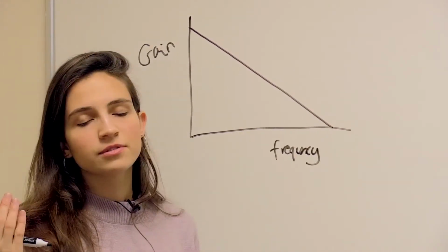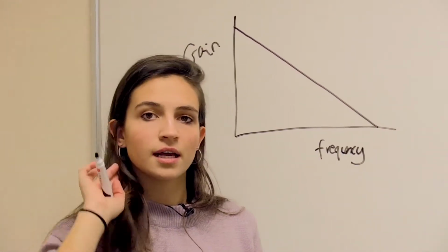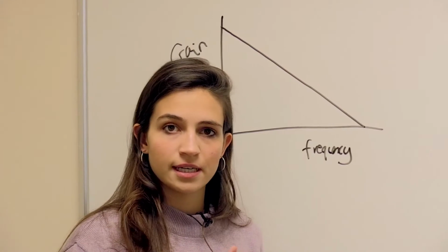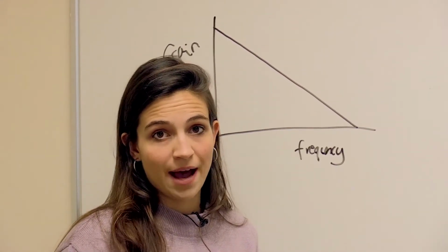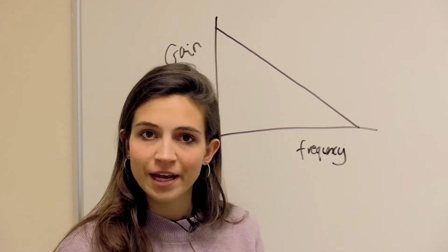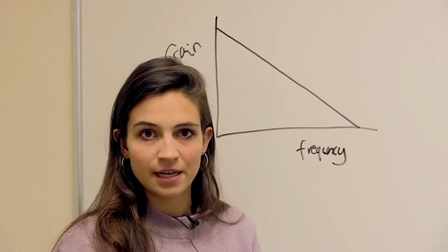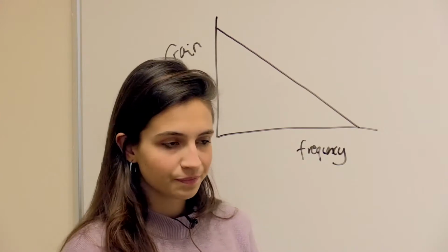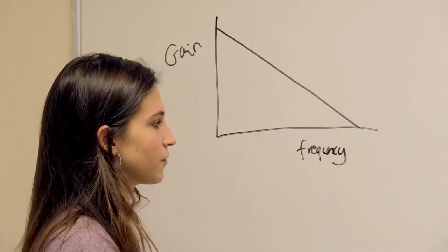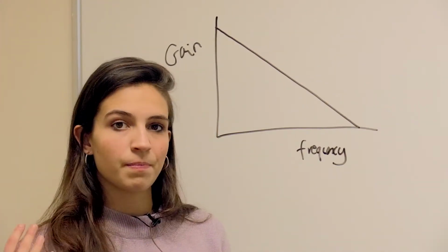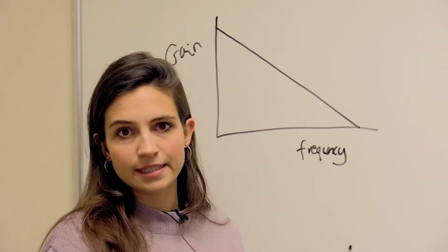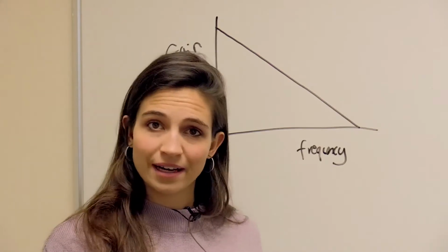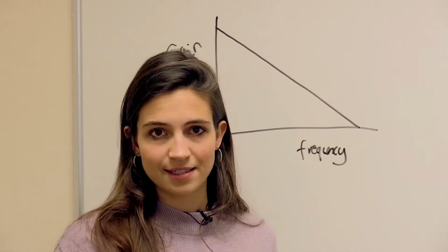So what adding the resistor to the circuit has done has meant that at lower frequencies, the circuit will now work as an inverting op-amp. And if you want some information about inverting op-amps, please have a look at the link below. But it means for higher frequencies past a certain threshold, it will return to working as an integrator, but without any saturation, so you get a clear signal.